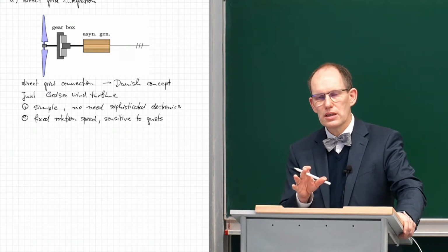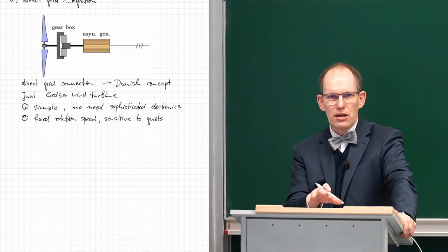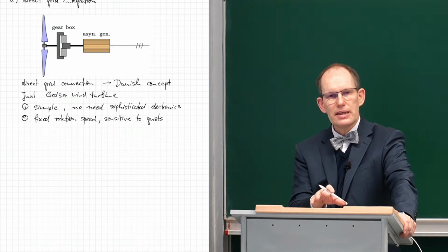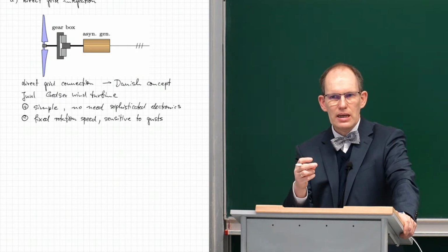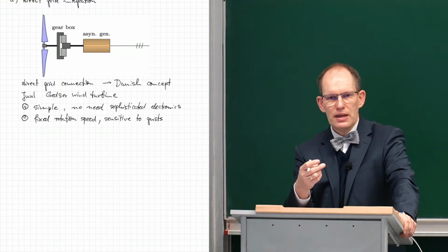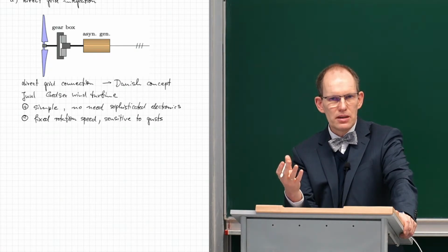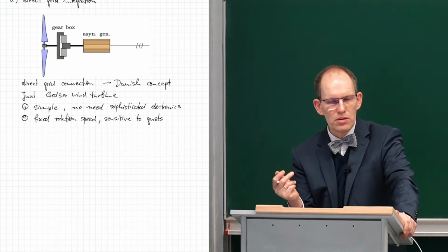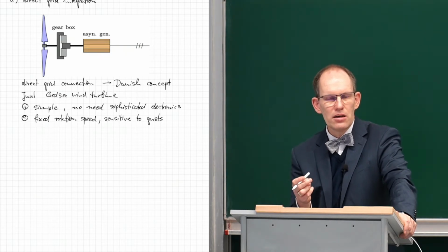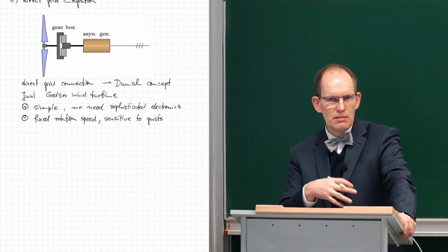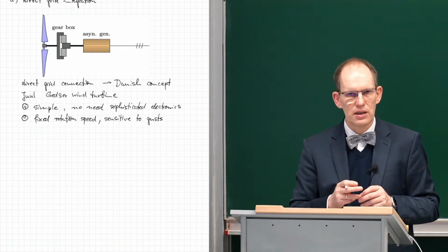So what you should keep in mind is that the electric concept of such a windmill has consequences also on the mechanics. If the electrical part is not flexible and does not smoothly respond to different wind speeds and thus to different mechanical loads, then this has a back effect on the stress on the entire machine.